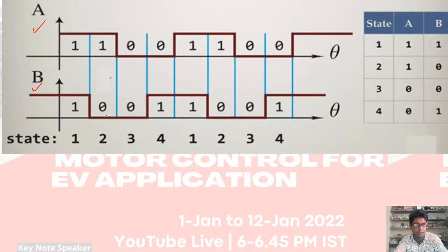Next is 1 0, next is 0 0, next is 0 1, and similarly the same state will repeat. Now if it is going from state 1 to 2 or 2 to 3 or 3 to 4, that means the disk is rotating in this direction.